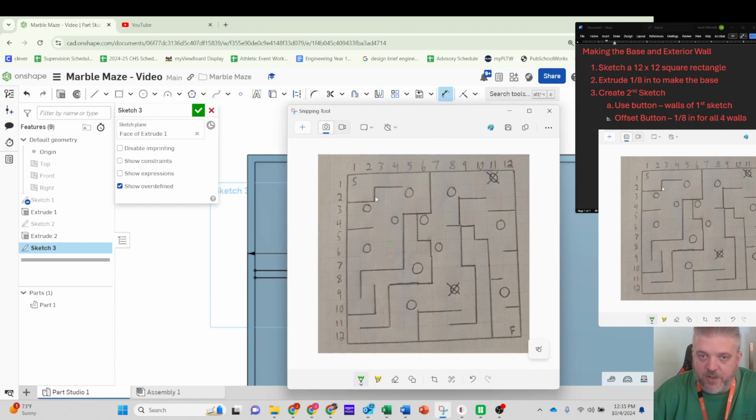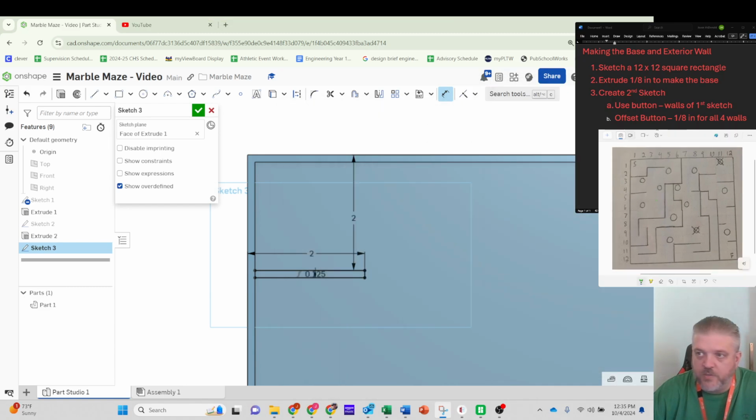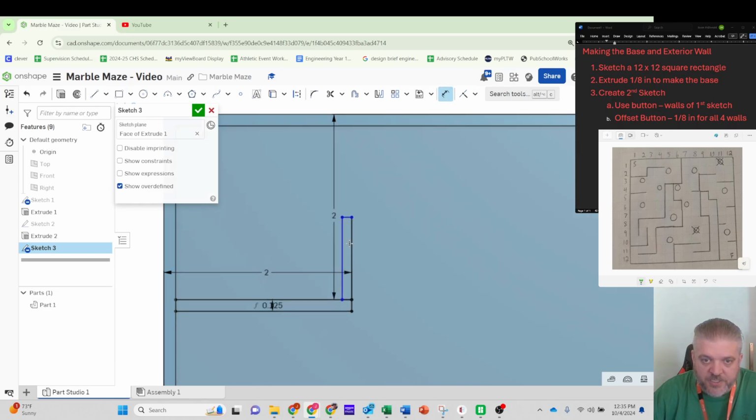Now from there, I had a 1 inch up, and then a 2 inch over. So we're going to make both those walls real quick. Again, we're making rectangles. I'm going to start from the corner here, click up, and go about 1 inch. I'm then going to dimension the wall, the outside to the inside.